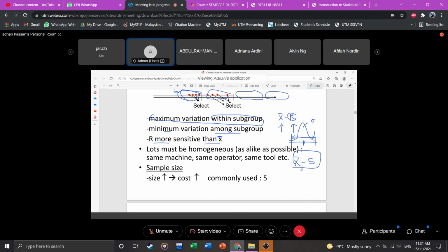But in the textbook, some exercises even give less. But actually in statistics, at least you need 10. But for R chart, you can have N equal to 2, because to get the R value, you just need two numbers, maximum and minimum. So it is cheaper to produce X bar and R chart compared to X bar and S chart.